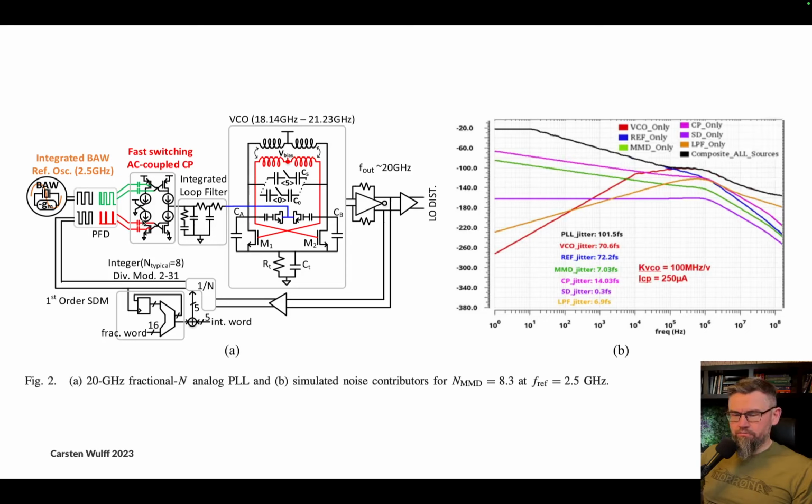I think they do that because, well, it's probably something with linearity and spurs, because when you turn the switch off or something, then I would assume that changes your current a bit. I'm not sure what they do here, but I'm pretty sure it's related to the charge that you feed in per clock into the loop filter. You want that to be the same and independent of the switching pattern that has come before.